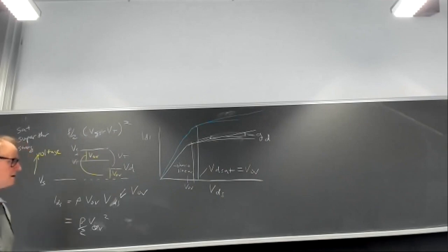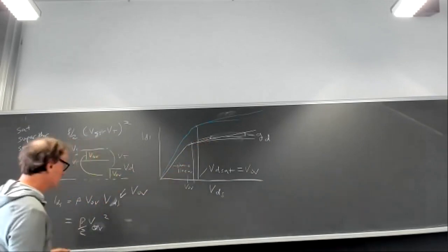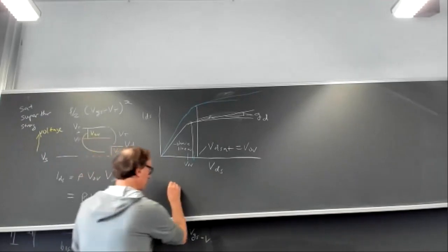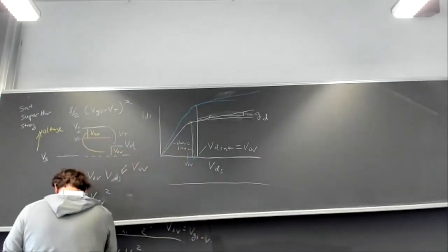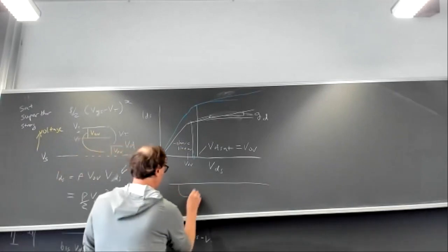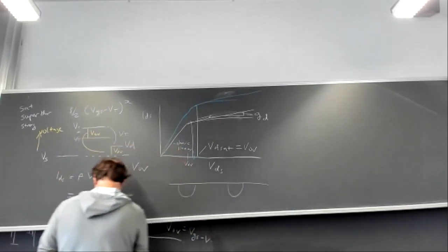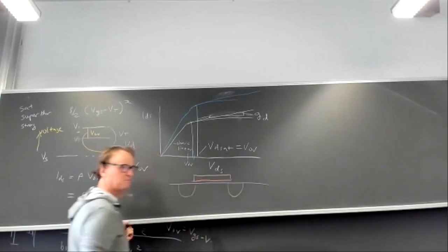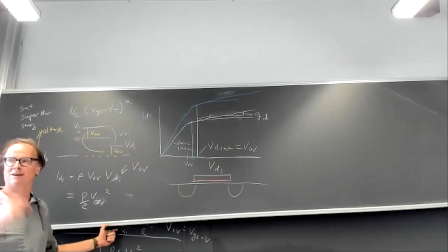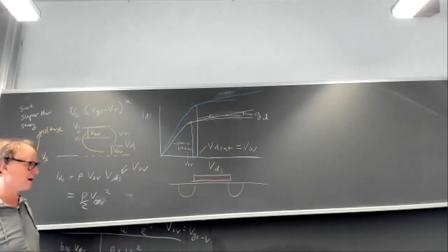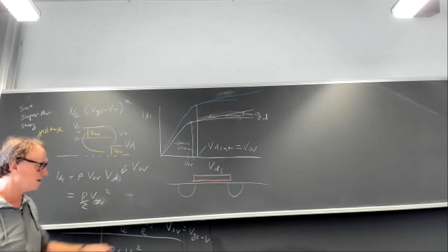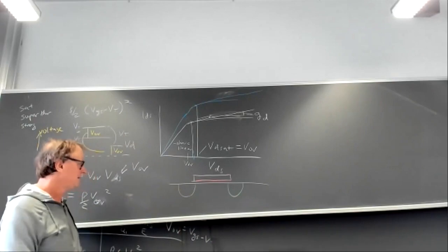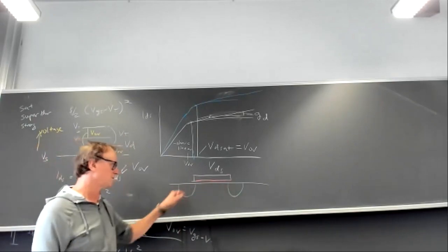Okay, so what do you think this drain conductance comes from? Let's draw the cross section of the transistor down here again, so we can speak about it a bit. Let's draw green for the source. And by the way, you know why they use red for poly? Because when you look in a microscope, the polysilicon actually looks red. That's why they always draw red. And green, the active region kind of looks greenish if you look at it in the microscope. This is called the active region of these doped regions for source and drain.